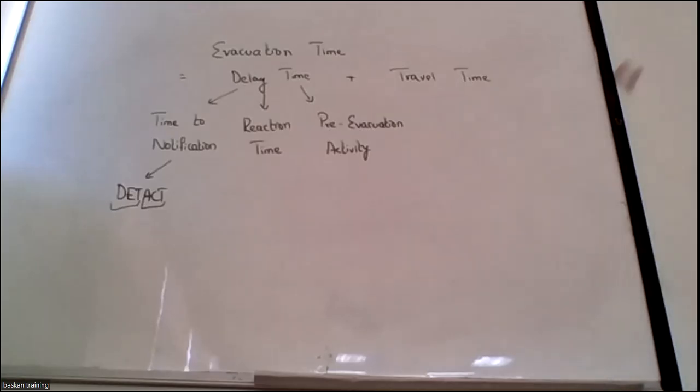We have discussed in the questions also, right? Smoke detectors are more rapid than heat detectors. So I cannot have heat detectors in this area. If I have heat detectors here, then the heat will reach 57 degrees Celsius at a time when the people will not be able to evacuate. It's over, it's the end. So the characteristics of the material define the detectors.